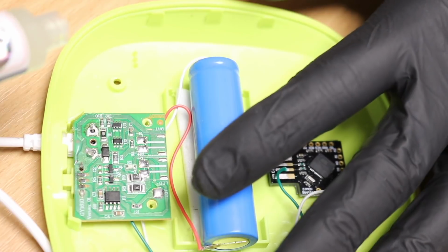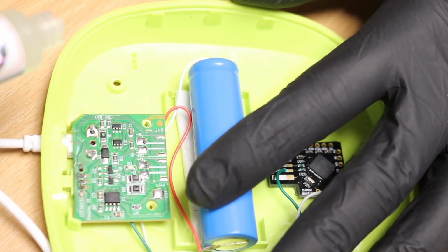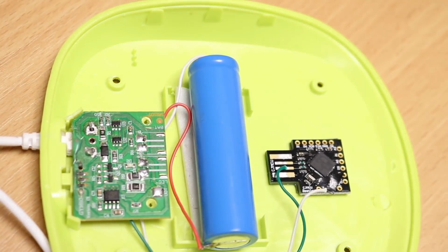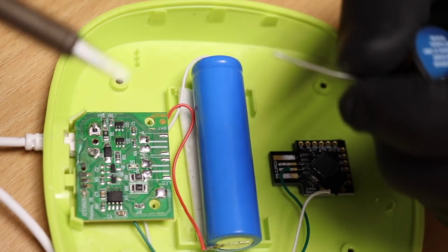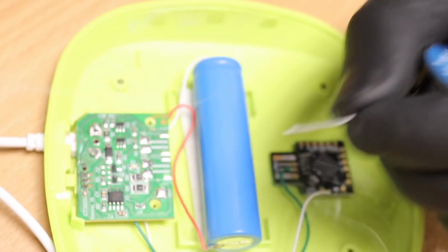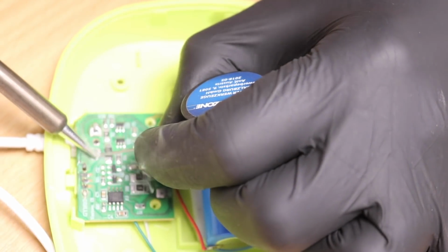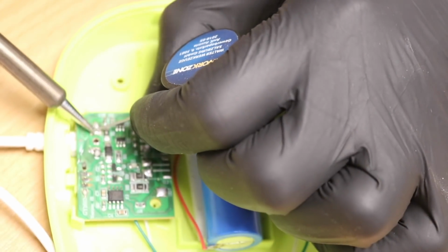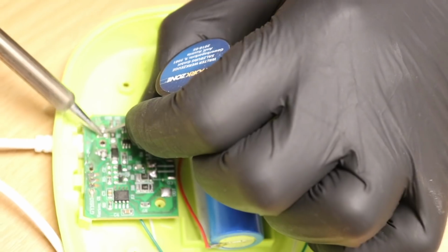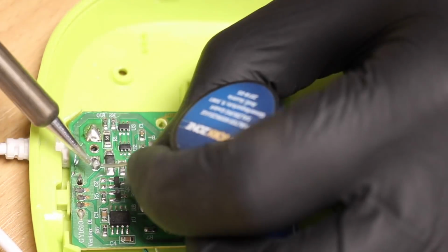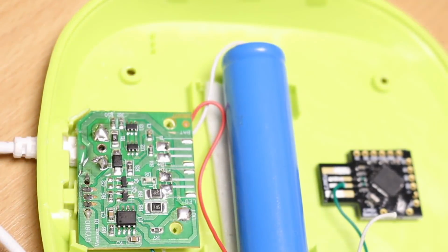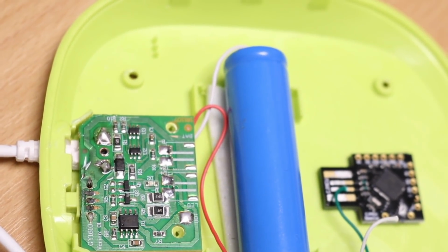So why do you apply the flux? Flux cleans the joint and allows the solder to spread nicely. So we're going to tin the tip and get to work. So this is for the power? Yeah, this is the ground point, and this is the positive point, which is here. There we go, those look nice. Ish. Okay, so the main points are resoldered, so the board should work on its own now.